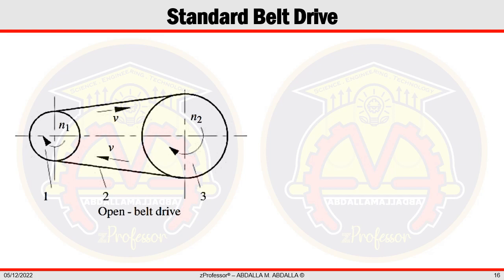The small driving pulley is put on the high-speed shaft when a belt drive is used to reduce speed, which is typical in industry. The large driven pulley is attached to the driven machine shaft. The torque will rise according to the speed drop. Machines must have features that allow for belt replacement and adjustments since belts are in finite loop.